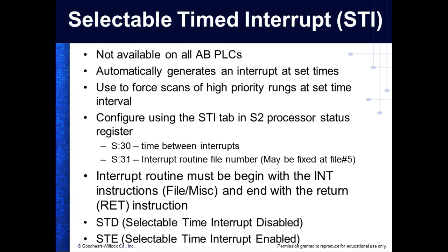You cannot use a standard discrete IO module to accomplish an IO interrupt. Yeah, well, we're still in the STI, but you're right. So this is STI. All you've got to do here is generated internal to the PLC. Y'all understand that? So you don't have to have a special module to do the STI, but your processor's got to support that instruction, right?